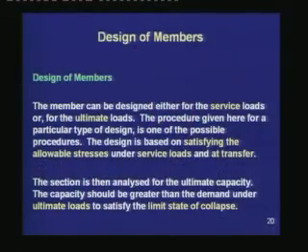The members can be designed either for the service loads or for the ultimate loads. The procedure given here for a particular type of design is one of the possible procedures. The design is based on satisfying the allowable stresses under service loads and at transfer. The section is then analyzed for the ultimate capacity. The capacity should be greater than the demand under ultimate loads to satisfy the limit state of collapse.